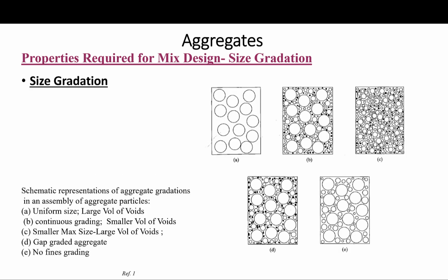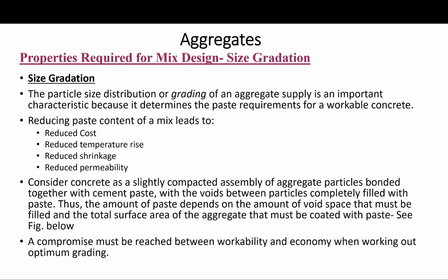Okay, so let's look at the size gradation. I'm going too fast here. Let's look at the size gradation. So the particle size distribution or grading of an aggregate supply is an important characteristic because it determines the paste requirements for a workable mix, as we will see later.